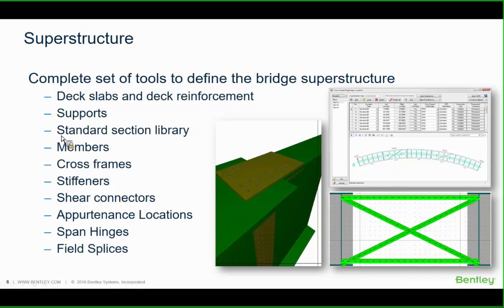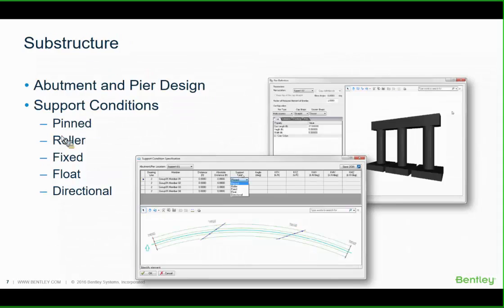And as far as the substructure, we have a library of piers you're very familiar with if you have used in the past LEAP Bridge Concrete or LEAP Bridge Enterprise, with different support conditions. So as soon as we define the structure, it brings in the substructure. You can go back into the dialogs and modify, for example, the shape of the column or the footings themselves, and you can make adjustments. So that's really wonderful.